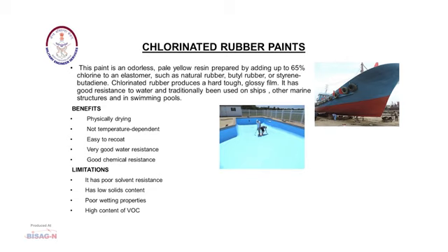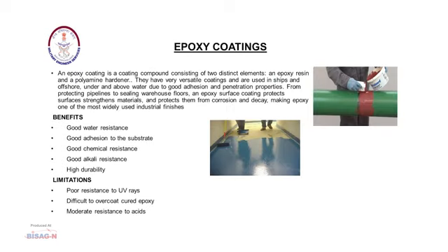The benefits: they are physically drying, no separate preparation or temperature is required for drying, easy to recoat, very good water resistance, good chemical resistance. But limitations: it has poor solvent resistance, low solid content, poor wetting properties and high content of volatile organic compound.